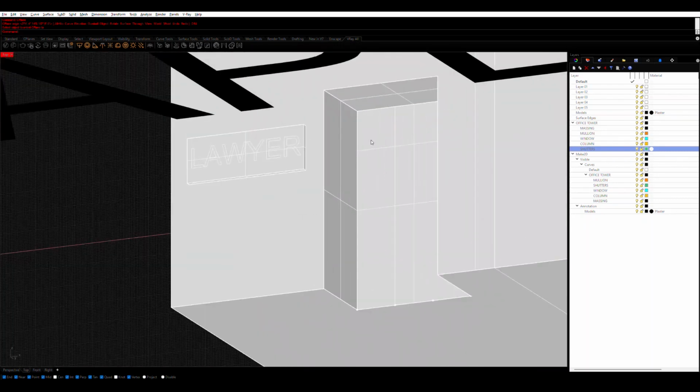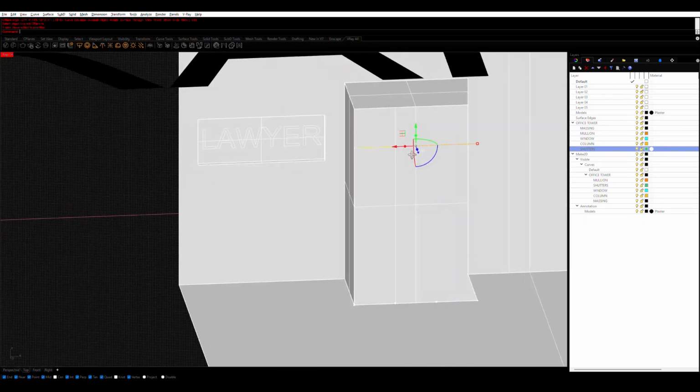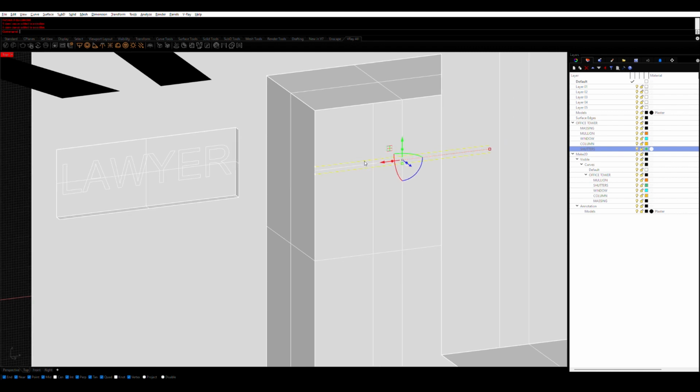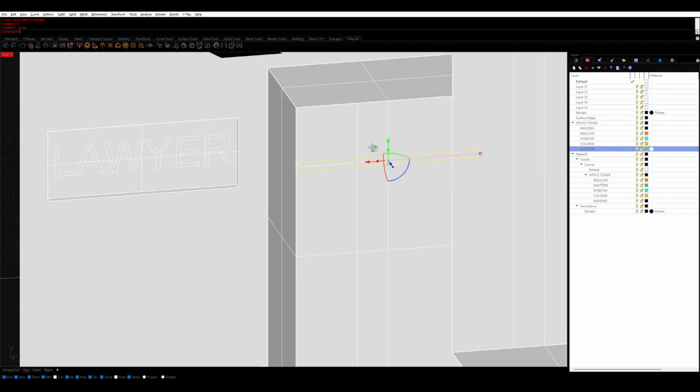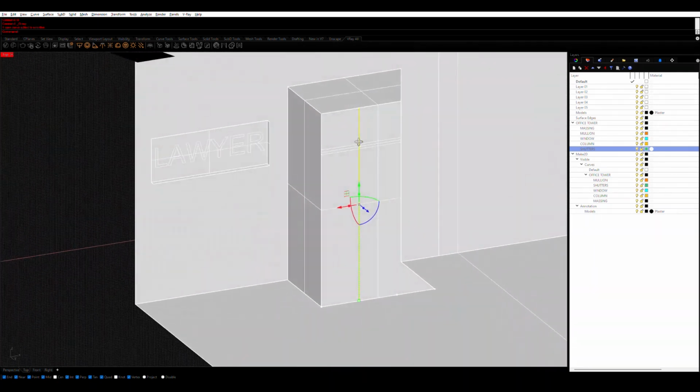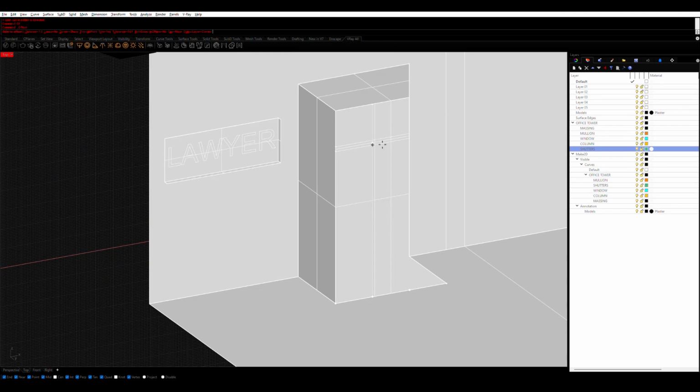In this case, I'm selecting that surface, and now our C-plane is aligned to this object. What I can do is offset this frame detail, say 1.5 inches on both sides. That's good. Let's group them for the time being. And from here, we'll also offset this, both sides. That's good.